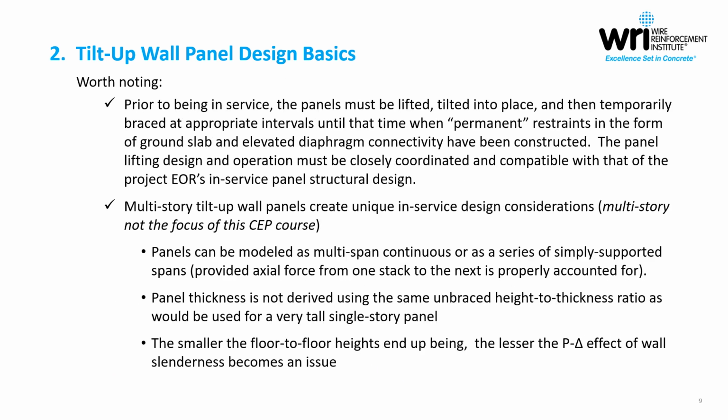Worth noting, prior to being in service, of course, the panels must be lifted. They're tilted into place, and then they're temporarily braced until permanent restraints can be constructed, such as floor and roof diaphragms, slabs on ground, that sort of thing. The panel lifting design and the operation itself really needs to be closely coordinated and be compatible with that of the engineer of record's panel structural design. The engineer of record is typically not doing the lifting design, but there needs to be some clear communication there.